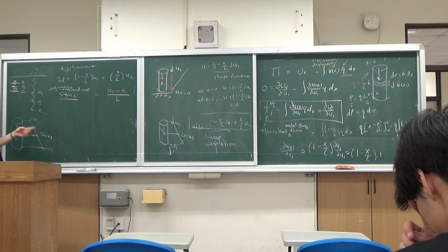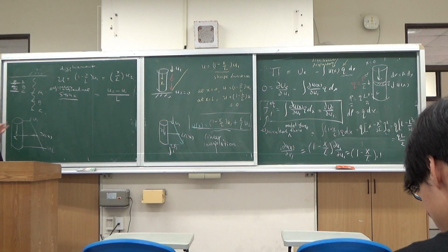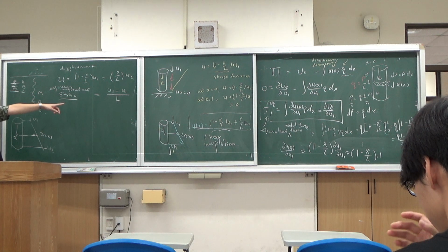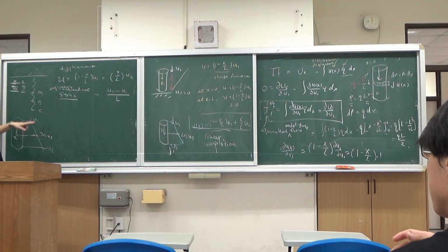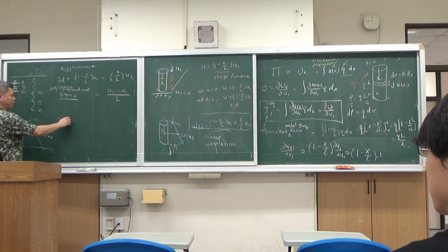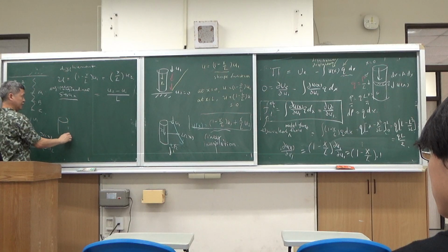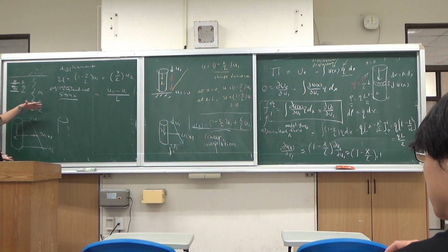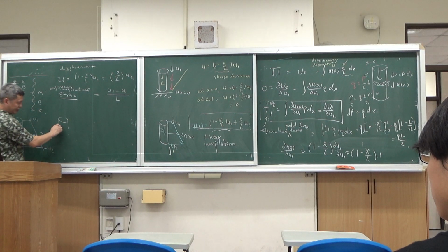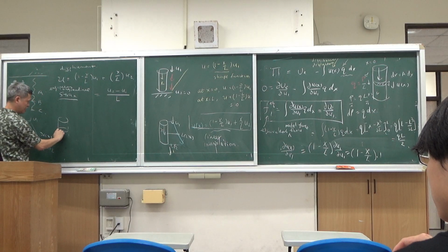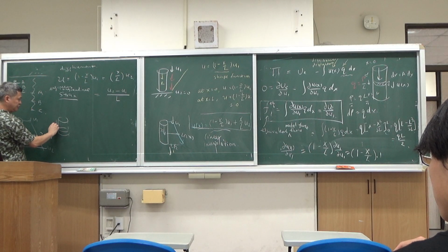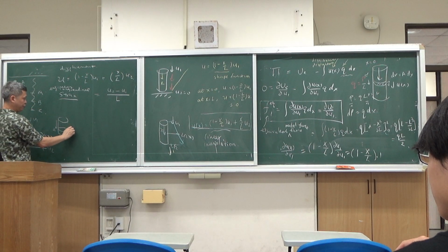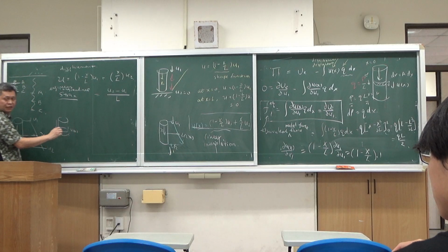And now, engineering wise, how do you define strain? Engineering wise, if you are going to define strain, you are not taking the total piece. You are taking a small piece. If this is location x, you might have displacement u(x).